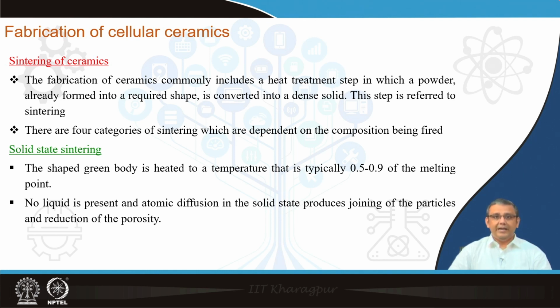That means we use certain pore formers like some kind of polymer or wax, or in freeze casting we use ice templating as pore formers. So, the idea is that the pore formers will provide the porosity, but the surrounding ceramic regions should be as nearly dense as possible to provide high mechanical properties.